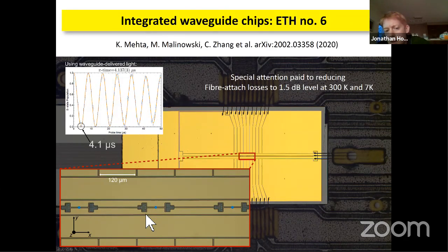One thing that is challenging is that in the fabrication, the gratings are put down in a different step to the electrodes, and the electrodes somewhat define the position of the ion. What it means is that the E-beam step used for the gratings has to be very well aligned to the step used for the electrodes, and that's a fabrication challenge that's still there. In the early chips, Karam was smart, so he just offset this grating from this grating from this grating a little bit, so that they're all a bit off. But what that means is that you can easily find one that's in the right place. So there are still certainly technical challenges to solve in that regard.